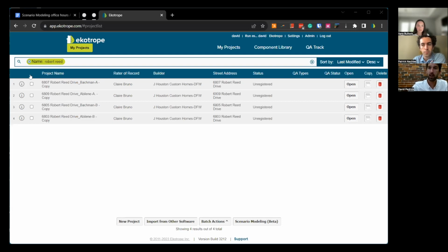One, the builder couldn't find radiant barriers, so they need to know the impact of not having radiant barrier. The other situation is they couldn't find the same types of windows they had originally planned for. Another is they couldn't find the same water heater they had planned on, so they're looking at what if we change the water heater. And finally, what happens if the infiltration is a little bit different? So I'm going to show you how scenario modeling is done in this case.